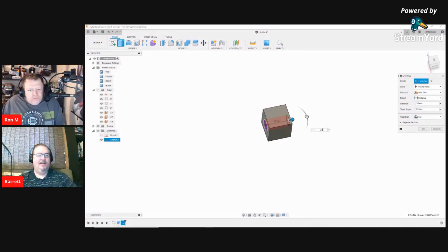It automatically recognized that you were going to cut the body, but you always want to look at that because that's probably the one gotcha. If you don't watch what that's doing, sometimes it'll select a cut when you actually want to join something, or funny business will happen, or you want a new body and you end up accidentally joining it. It's useful to keep an eye on what's going on there and make sure that it's going to do what you want. When you're happy with it, just click OK.